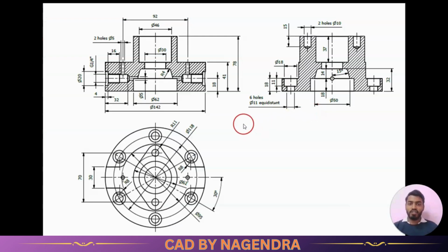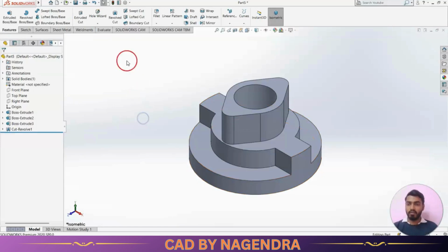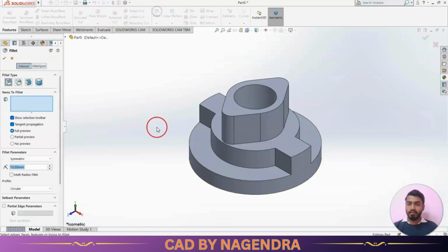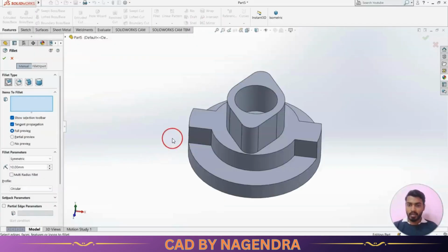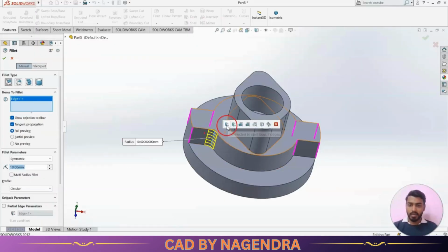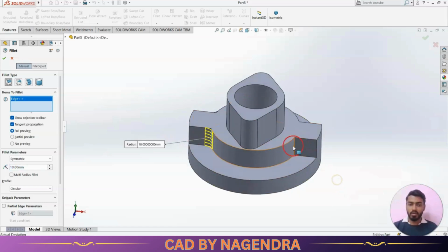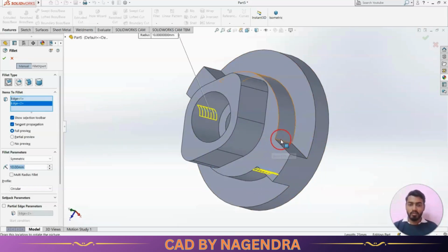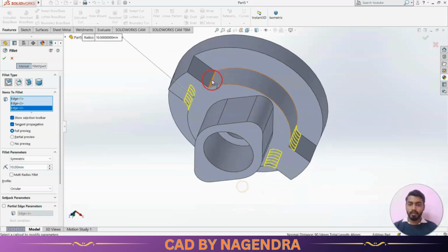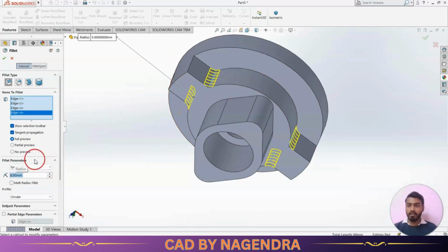Then all addition of material done, all this removal of material done, then directly we can go here with any fillets if anything is there. As you can see, fillets we are having for these edges with radius of 8 mm exactly here. So let me apply fillet for those edges. We need fillet exactly here, these edges. By selecting that, we will check whether we are able to select edges. It is not possible to select whatever we wanted, so manually we will select here. We need here radius of 8, let's say okay, like this.